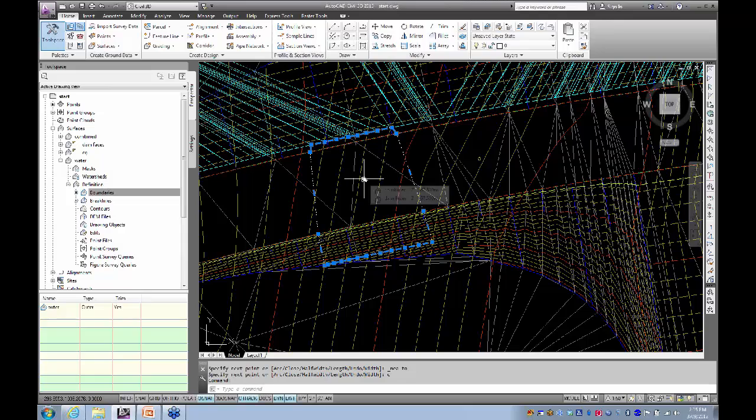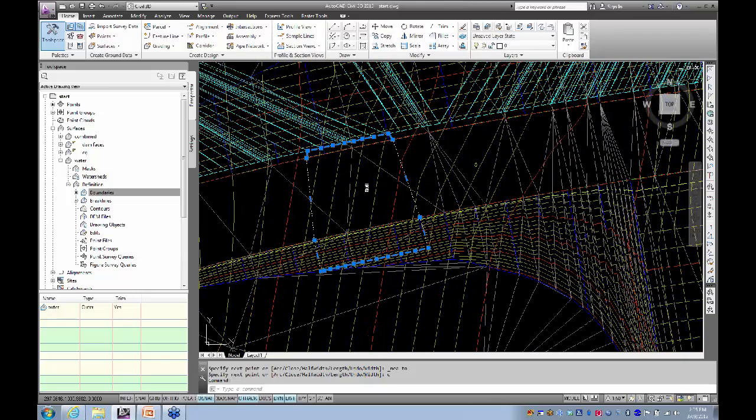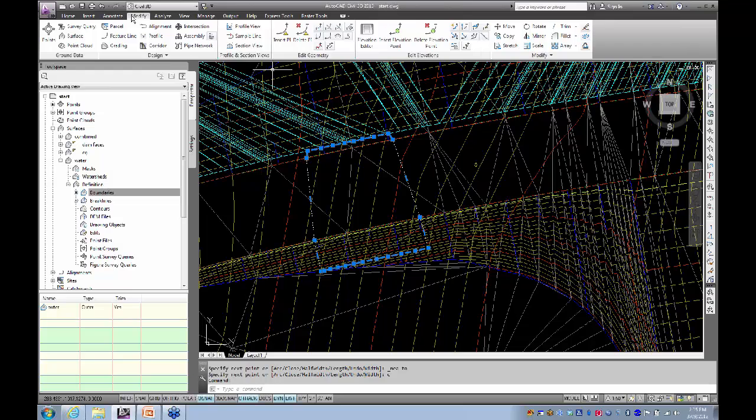So let's just show you how the drape command works. And this might pick up if I haven't snapped it exactly to all of the endpoints on those contours as well. It'll actually smooth that out for us too. So let's do that. In the modify tools in the ribbon, there is a command over here to grab elevations from a surface. So I'm going to grab that.